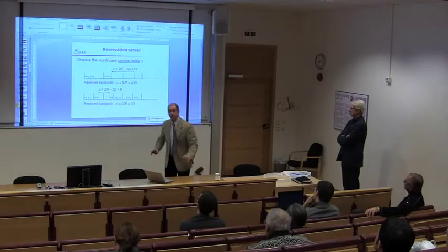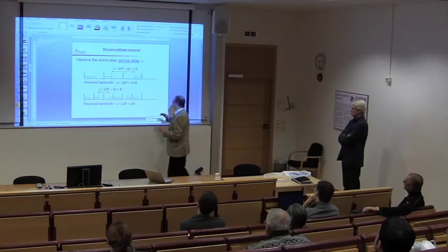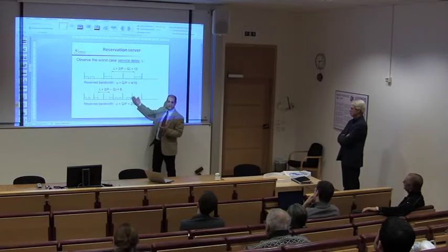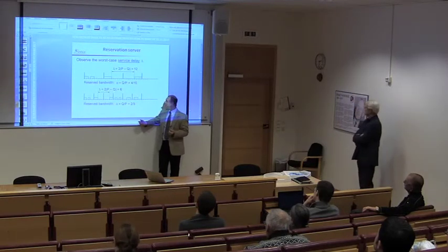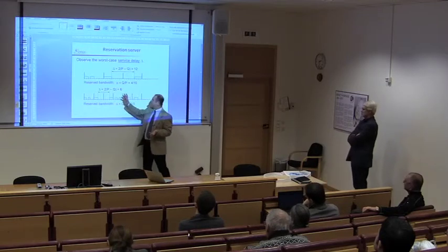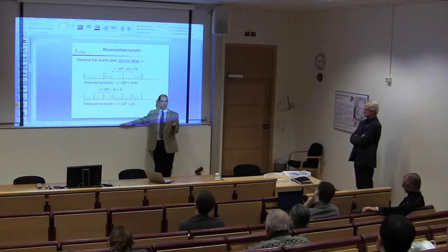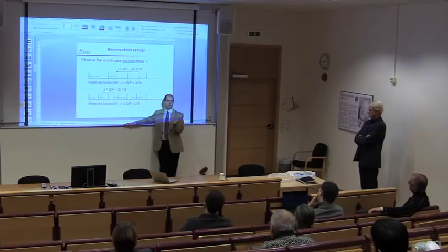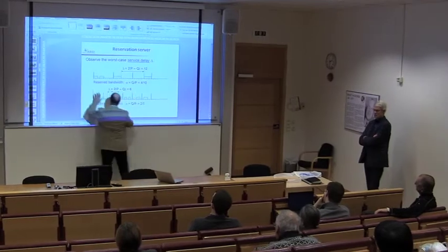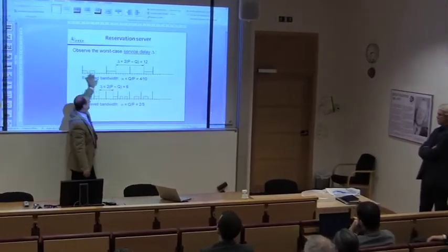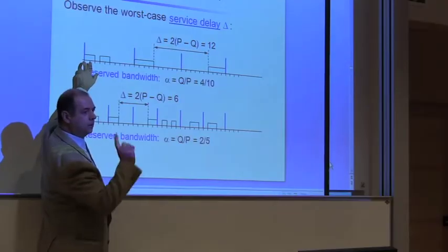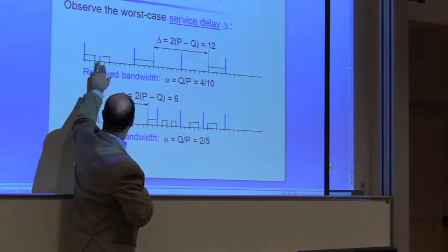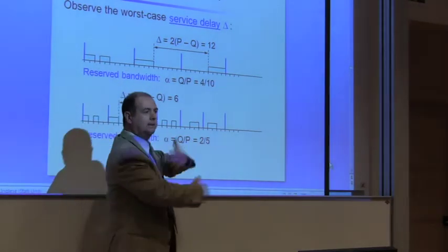Okay, the question is, when we implement reservations, should we use a slot-based approach, or can a priority-based approach also work? Well, you can use both, because a slot-based approach is for sure one approach you can use to partition the processor into different reservations. In this case, these slots are fixed, the same in each period. Typically, you say, for example, these 2 units are allocated to application 1, and then these 2 units to application 2, and this repeats the same.